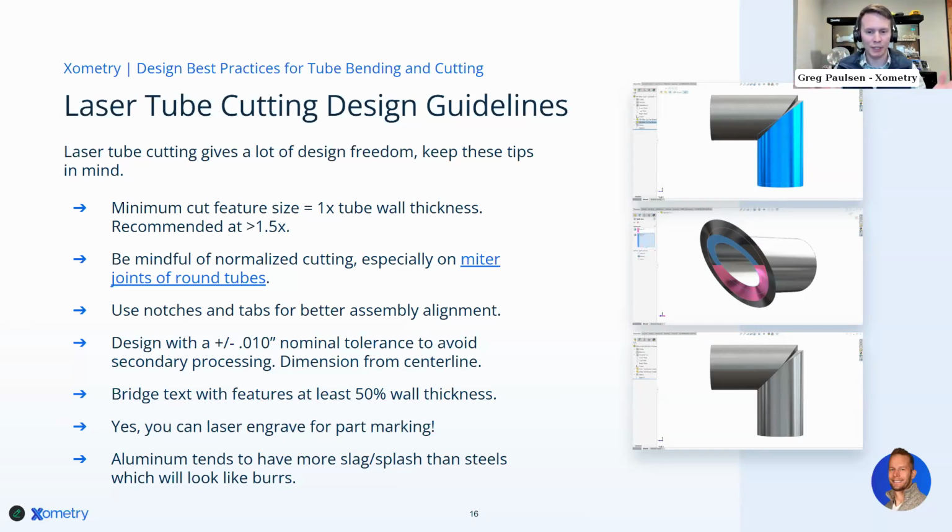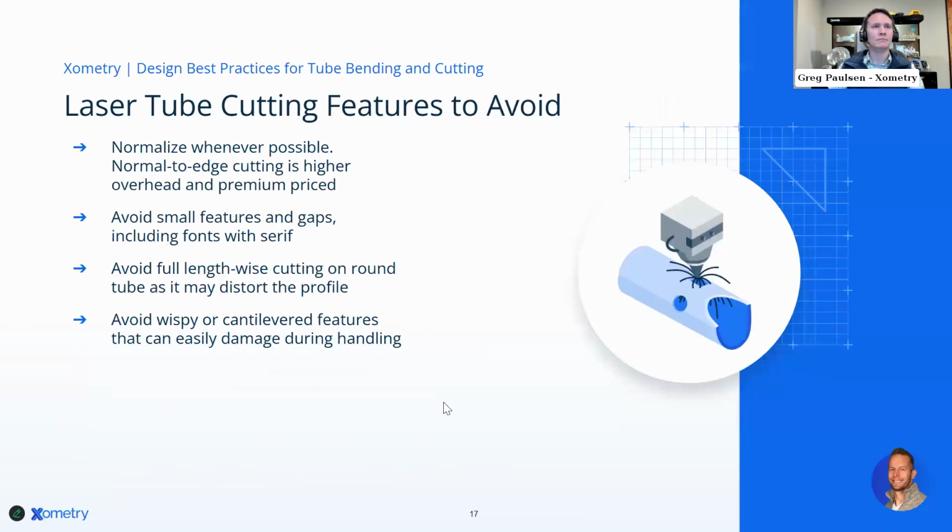And by the way, fun fact, because I work in advanced additive manufacturing, when you're doing metal additive manufacturing, the same rules apply for aluminum 3D printing and steel or stainless steel 3D printing, where you usually get crisper features on the stainless steel over aluminum because of that thermal conductivity. Yeah, so keep in mind, aluminum is a great material, but if you're cosmetic, maybe steel is your better choice, or stainless steel. So yeah, moving on here.